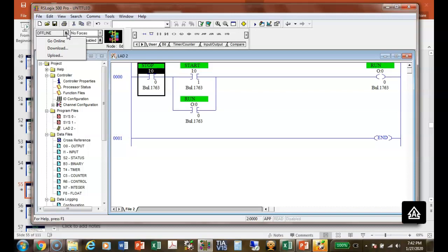Well, the way PLCs look at it, and we can look this up, if I use a normally open push button, what happens if the wire opens? It's going to be open, and we couldn't stop the circuit, right? You understand? So what we're doing is we're saying this is an examine if closed. So it means this contact is true if it's closed, and we'll have to go down there and show it to you because, like I said, I can't connect to my PLC. So let's see.